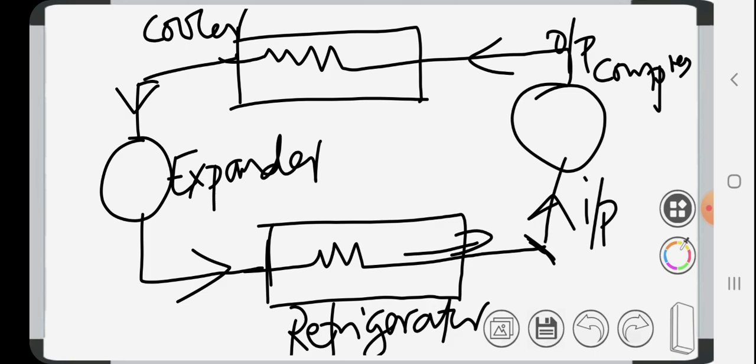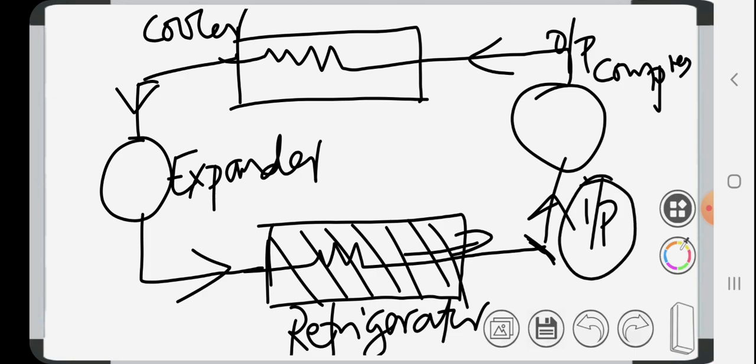But in case of open refrigeration, the system is open to the atmosphere. Atmospheric pressure is lower compared to the pressure inside a pipe. So the input pressure in case of an open system will be very much lower. So the pressure ratio required for the compressor to reach this output pressure will be even higher. So the compressor should work at a higher pressure ratio, the suction, right?